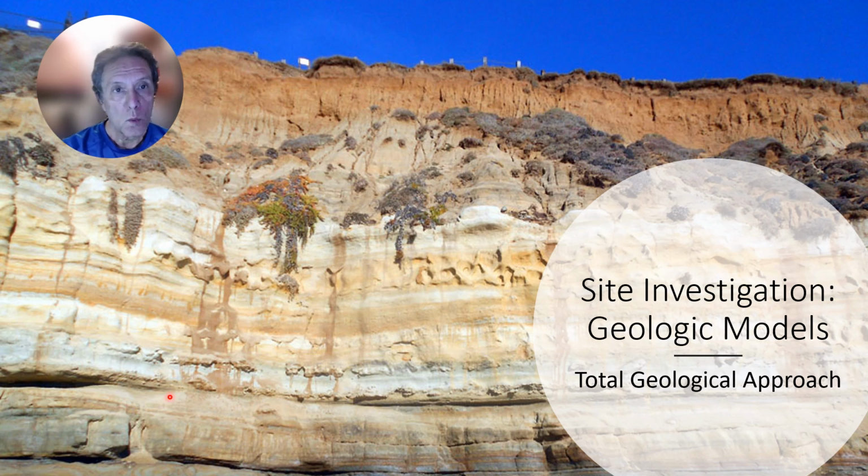So you want to come up with a geologic model for each property you're investigating, whether it's founded on shallow bedrock or deep bedrock, deep soft soils, high groundwater, expansive clays, whatever conditions are present and existing which will affect the construction and design of the project must be assessed, must be characterized, must be identified.